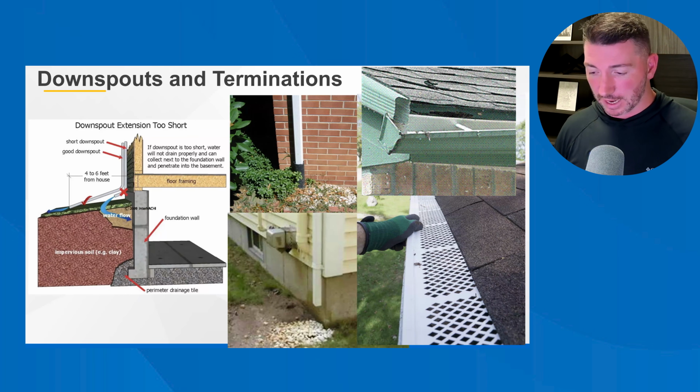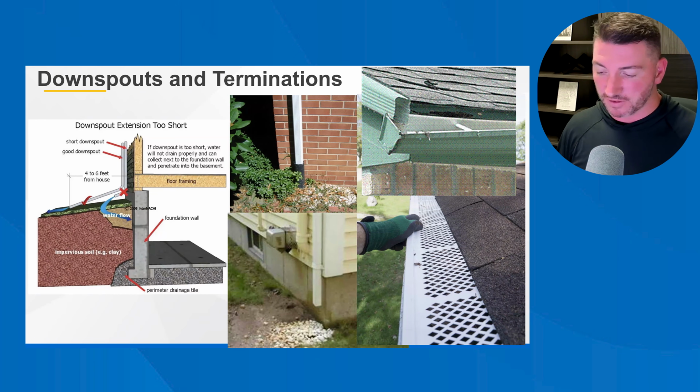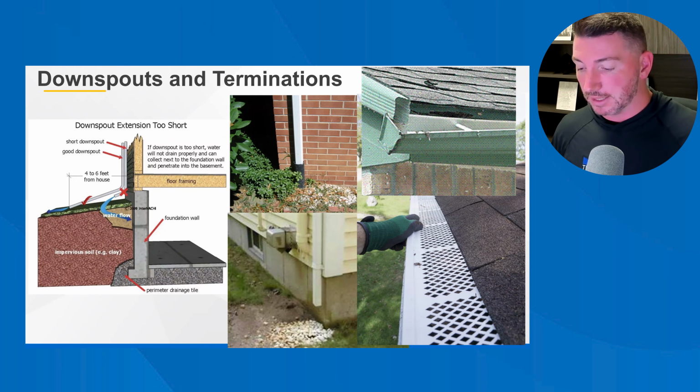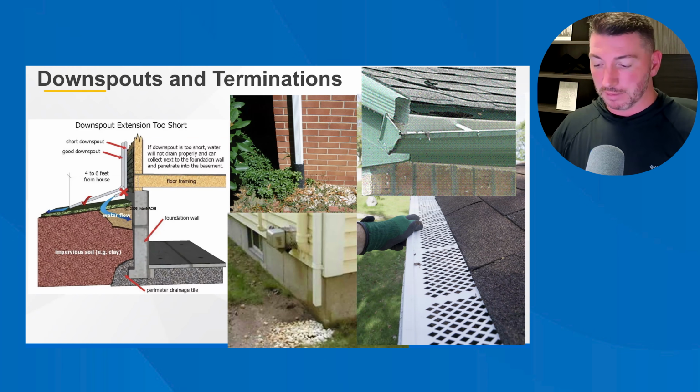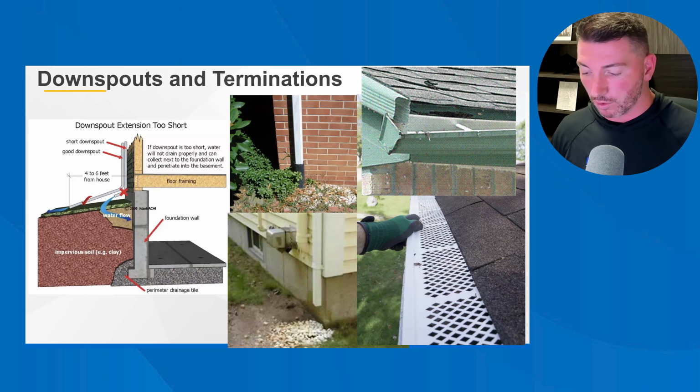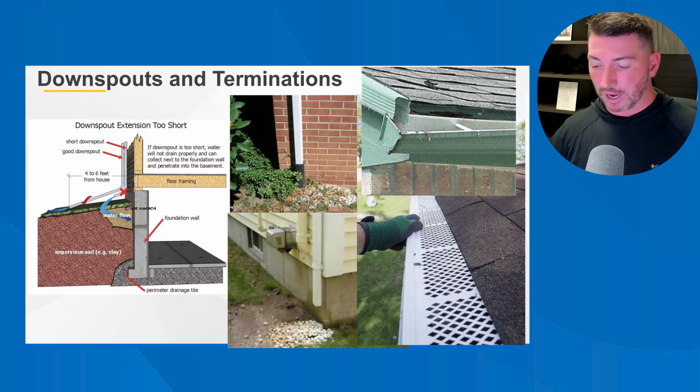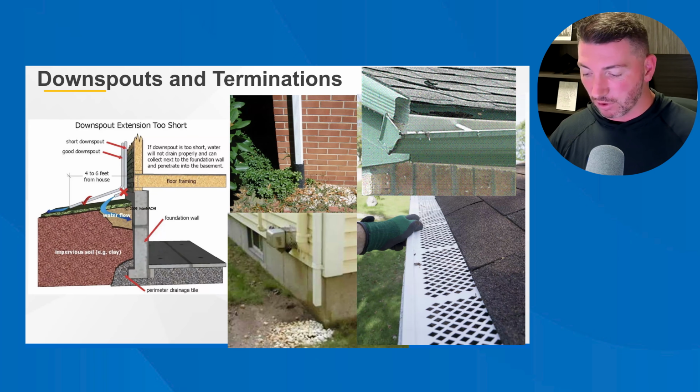So for, again, a 30x50 house with a 4/12 slope, you've got a 1,500 square foot footprint, and then a 1.054 slope factor results in 15.8 squares, or 1,581 square feet. That assumes a simpler gable with no hips and valleys, but again, it's all kind of rough math anyway. If there are typical rake overhangs and eave overhangs, say 12 to 18 inches, you'd add roughly 10 to 15% more material, bringing you to around 17.5 to 18.5 squares of actual roofing material needed.